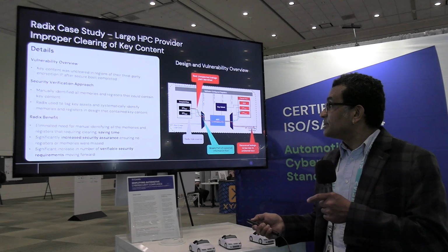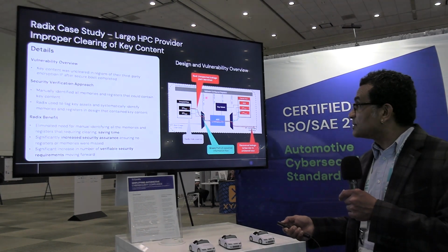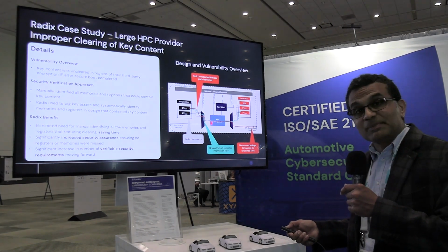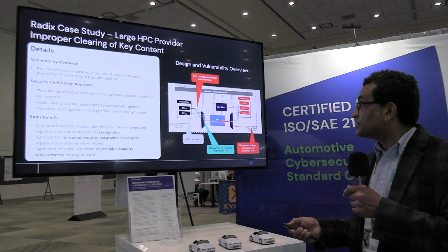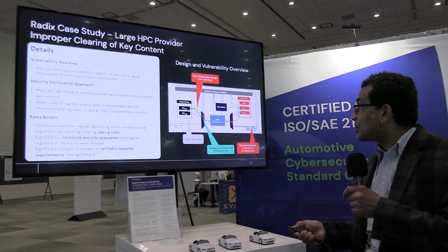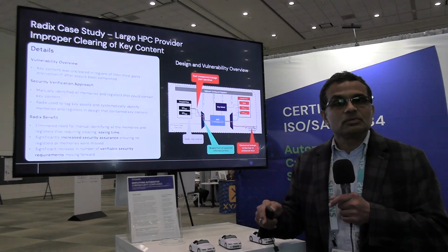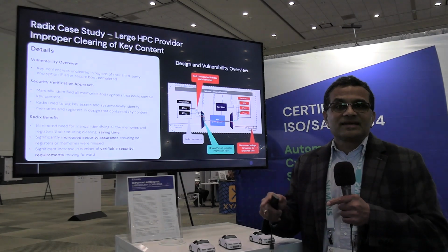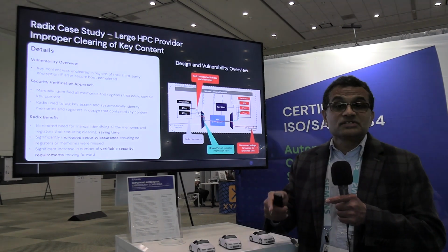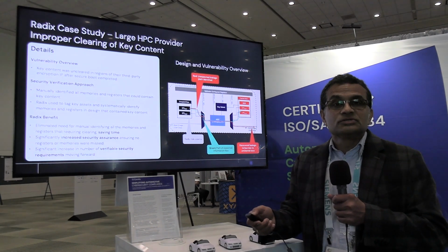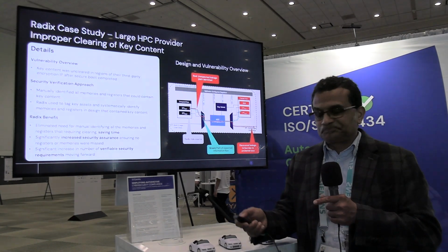Now this is an actual problem that happened. What happens is that there are remnants of the ciphertext key that were decrypted and saved in the AES block in the various pipeline stages, and that leaked out during just normal, regular, functional running of the block. This kind of bug or this kind of security weakness cannot be identified or located by functional verification. So information flow tracking allows the user to catch issues like this much in advance.